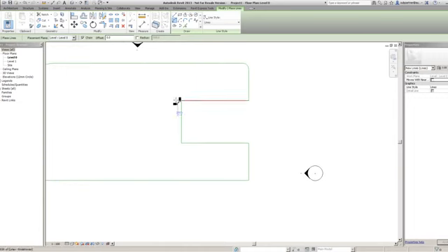Okay, let's just say I want to draw a nice half circle along this plane just here. What I'm going to do is this. Left click just there, then come down to here and left click. And what it does, you can actually draw in the radius, but it will snap to the tangent point, giving you the same radius to equal the diameter between the 2 lines that we've picked. Done. Perfect half circle from there to there to there.